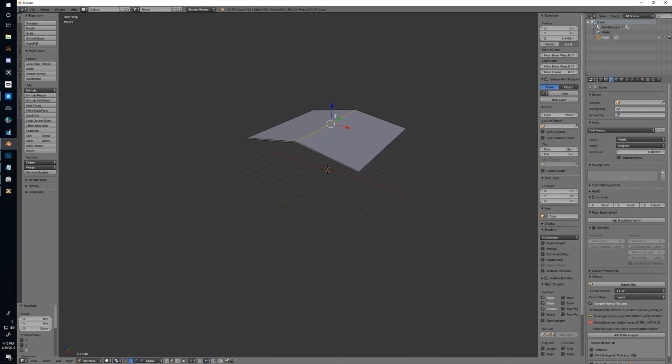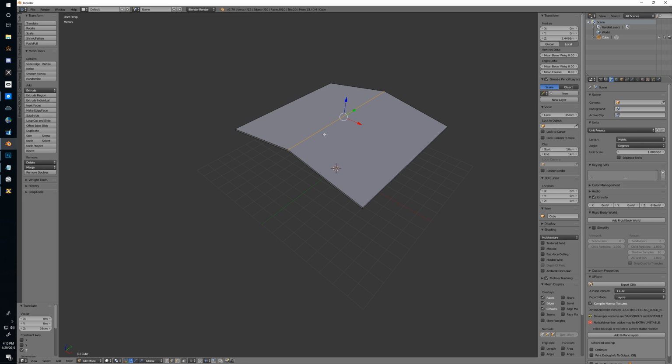Alright, and you might wonder why I did the roof this way first, just floating that way. Usually when you go through a tutorial like this, they tell you to put a cube down and then add the roof on top of it. But I kind of like this technique. Two things are going on. One is most of the aerial photos that you'll have, at least the ones that are immediately top down on a particular object, will be showing you that the outline of the building will be the outline of the roof, you know, and so any overhanging the roof is doing is going to be essentially what you're seeing.